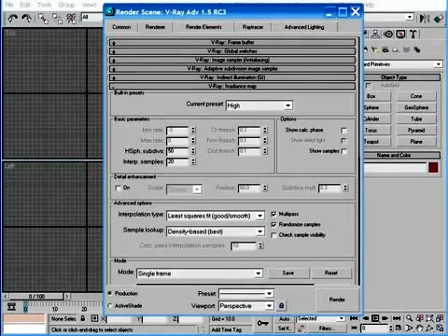And to do this, VRay renders a camera's view in a number of different passes, starting with a low resolution pass and progressively working up to a higher resolution pass. And within each of these successive passes, VRay determines if GI is good enough in each area of the rendered view, and if it's approximated well enough by the samples taken in each of these passes.